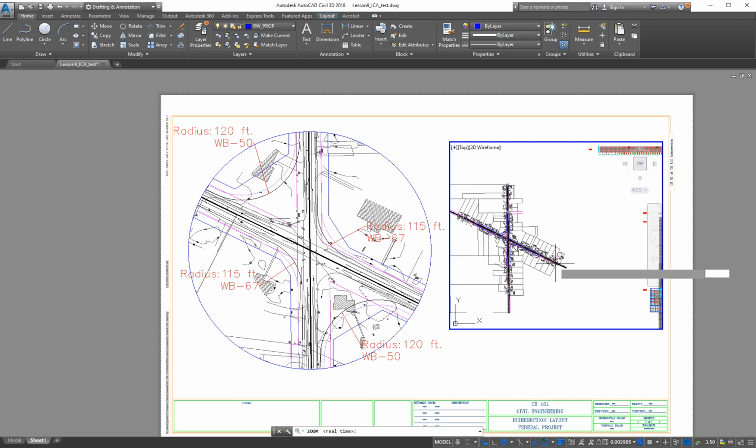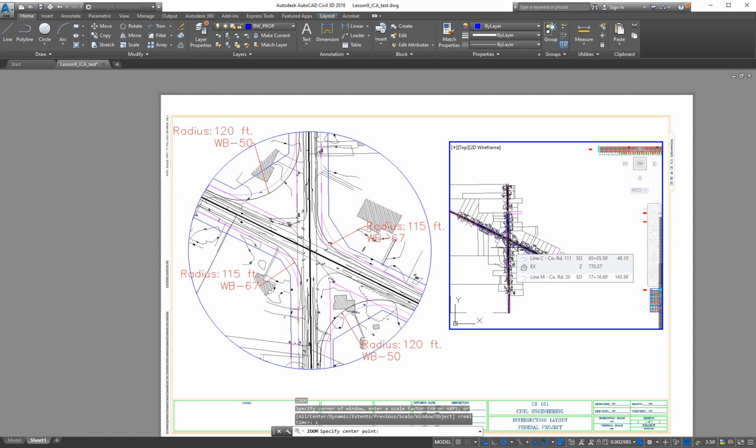I'm going to do zoom center, Z spacebar, then C spacebar. So I'm in zoom center. And what center point do I want? I can click something as the center point, or I can give it the coordinates. I'm going to give it coordinates, and I've got them written down here. So it's 25669, comma 2327998. Right. We hit enter.